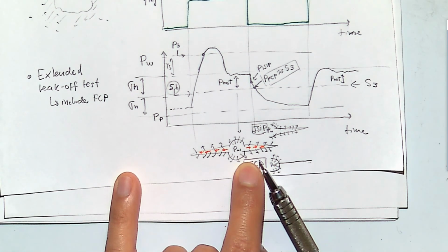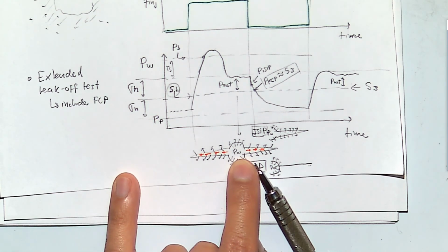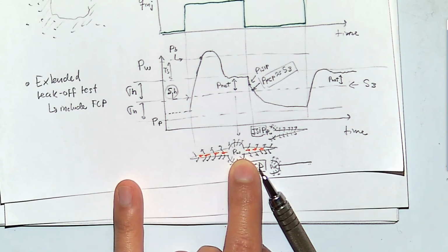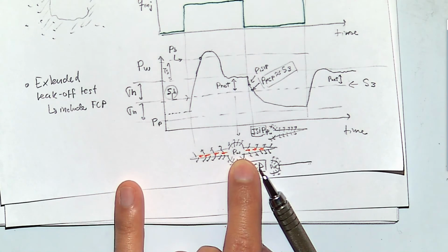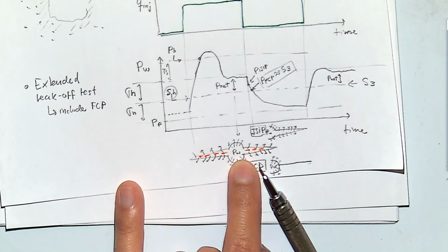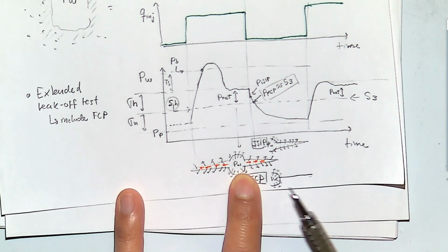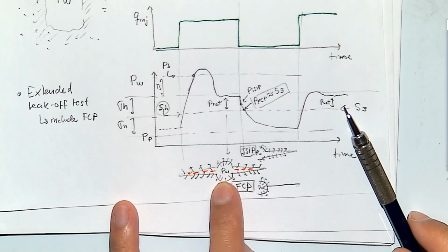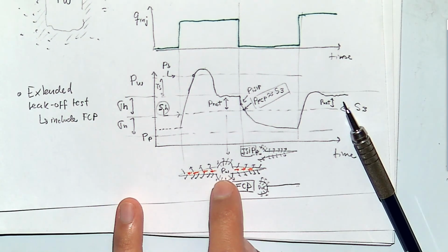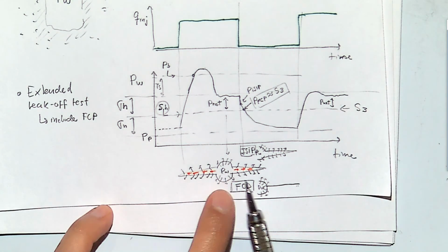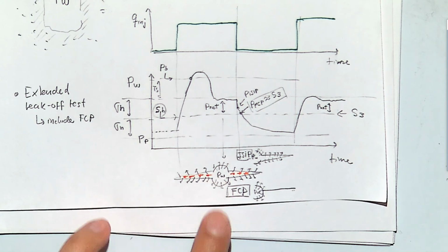Here, it appears that I'm making fractures that are several inches wide. But in reality, in a real formation, these are going to be actually quite narrow fractures. And flowing fluids through those narrow fractures is going to take quite a bit of energy that's going to be dissipated through viscous losses as you flow the fluid from the wellbore to the tip of the fracture. Okay.